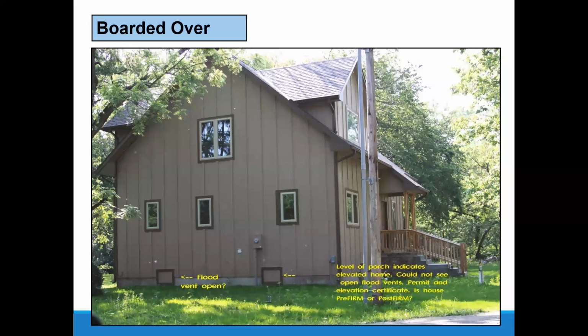And as far as flood openings, people really dislike having them in their structures. I'm not sure why it's such a big deal, but people are often boarding them over. We've heard that it makes the floors cold, and more typically it lets pests in, like raccoons or other animals that could get in through the flood openings. They can be covered, and I'll talk a little bit more about coverings, but they can't be completely closed in such a way like this house where they have just boarded over the openings.